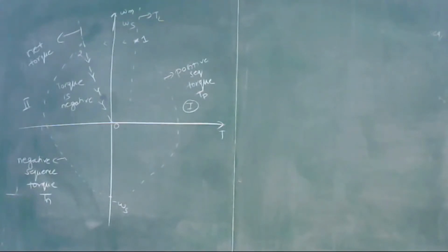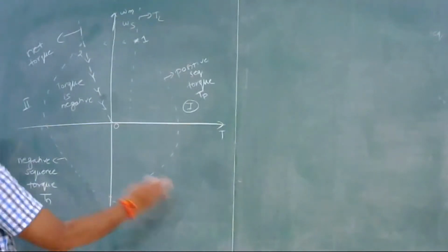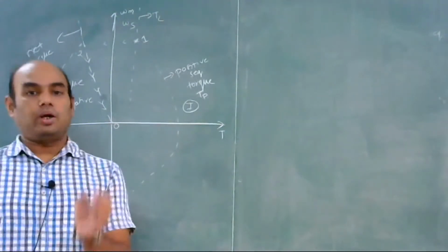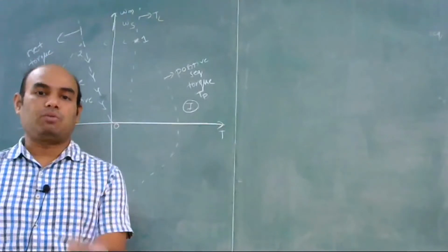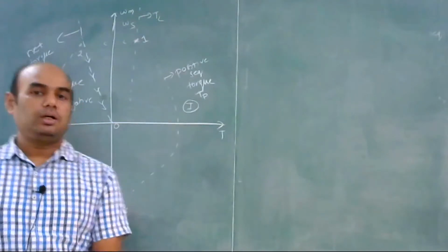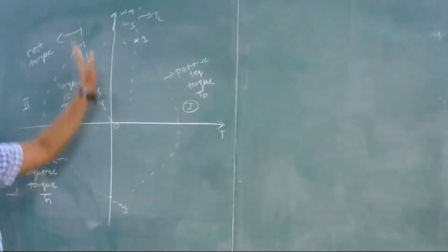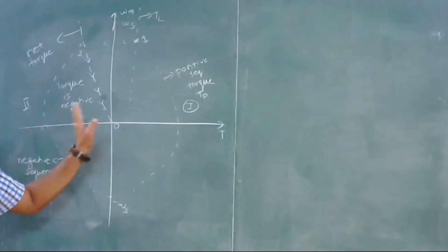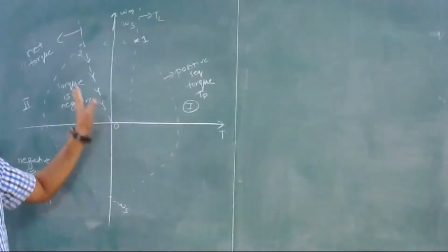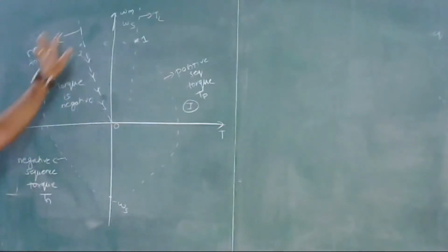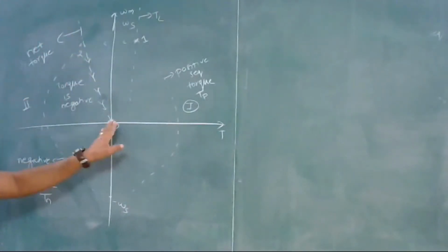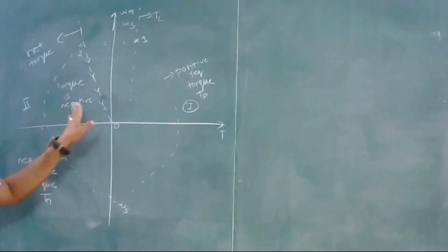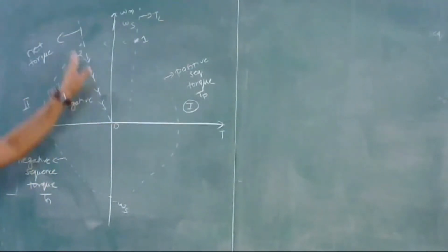So by suitable choice of resistance, braking torque can be obtained in the entire speed range. The choice of rotor resistance is very important, as this will ensure effective AC dynamic braking. We have to choose such a high resistance that the net torque characteristic lies in the second quadrant, that is, torque should be negative. Then only can we get the braking of this induction motor.